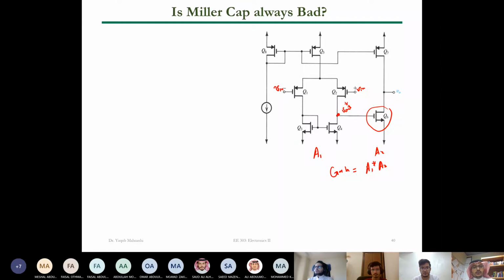Because if you have more than 3 poles, and you apply negative feedback, for example, this is an op-amp, right? And by the way, this is an open loop op-amp, still not in a feedback connection. We want, for example, to extend the bandwidth, so we want a negative feedback connection. But you need to be very, very careful before doing so, because if you apply feedback right away, the system may be unstable at some point, because you have a number of poles, maybe 3 or more. That is the condition we said you have to be careful about.